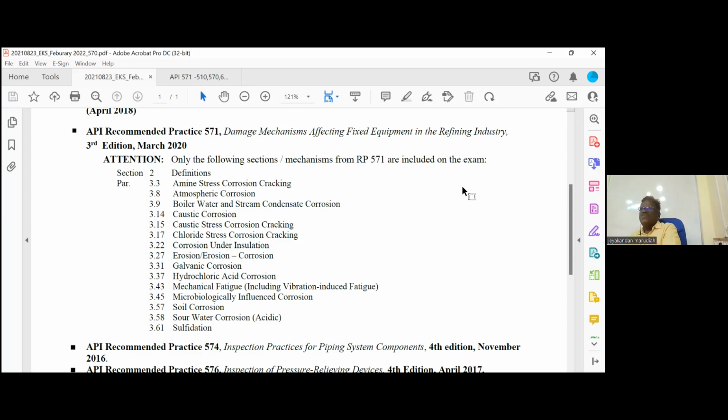The answer is, we have to keep a probe permanently in that location where you have a doubt and monitor continuously. It is not a repeated NDT technique. It is called a dynamic NDT. Only when the crack develops can we see it. When the crack stops, there will be no signal. So generally, they use it in piping and pressure vessels.